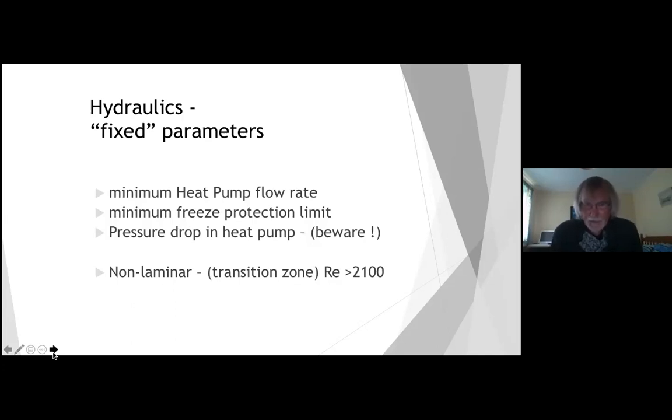And the other thing that's a given is the pressure drop in the heat pump. There's very little at that minimum heat pump flow rate. You can't do anything about the pressure drop in the heat pump. And I would just put a warning out. Closed loop ground source heat pumps really should be taking care of. There are heat pumps out there that really have very significant pressure drops on their heat exchangers.